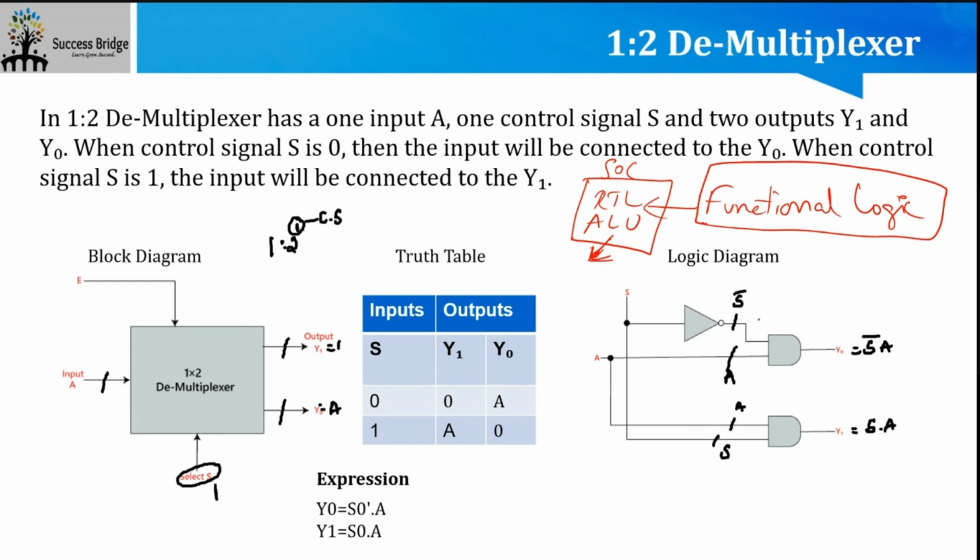Okay. So for that reason, we have segregated the RTL logic as functional logic, and the logic that you insert as part of your DFT insertion as DFT inserted logic. So what we care about is only the DFT inserted logic, which will be simple logic gates and 2x1 multiplexer, and flip flops.